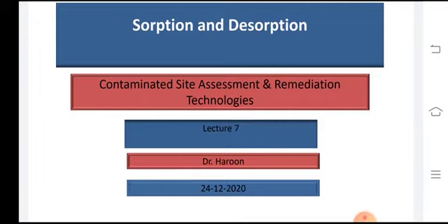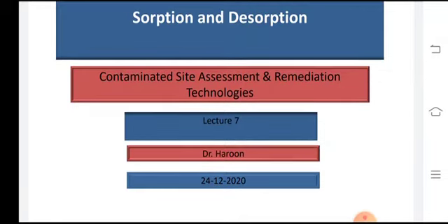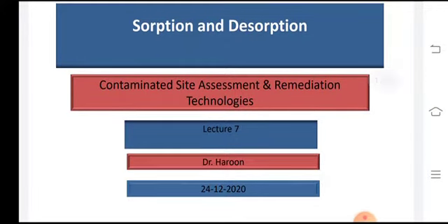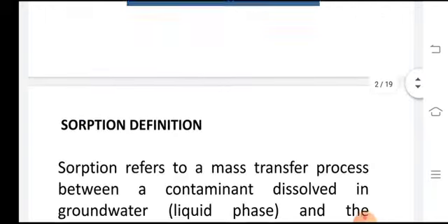We need to have a breakthrough curve for the concentration versus time variation. So at a particular location, how is the concentration changing with respect to time, and how is this concentration existing in equilibrium? Firstly it will be found in the aqueous phase, then it gets attached to the solid phase. So we need to have an equilibrium between the concentrations. The ratio between the amount in the aqueous and in the solid phase must be balanced. So let's talk about it in detail.